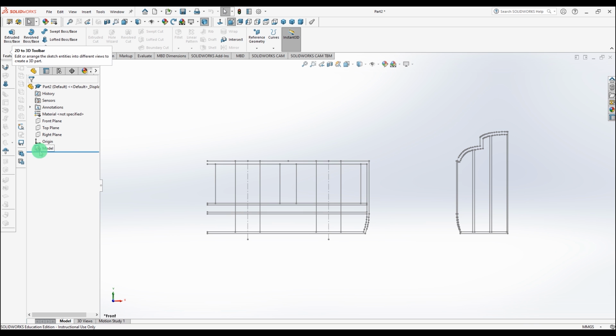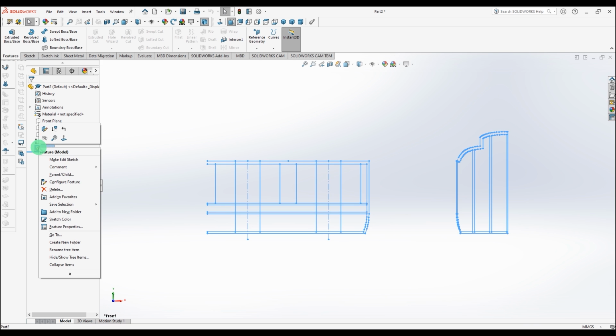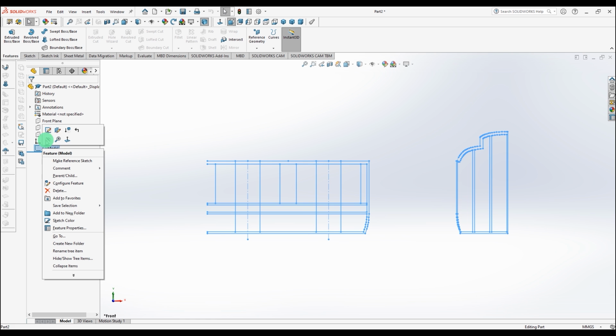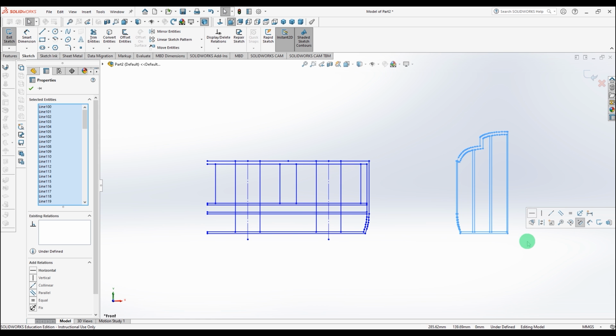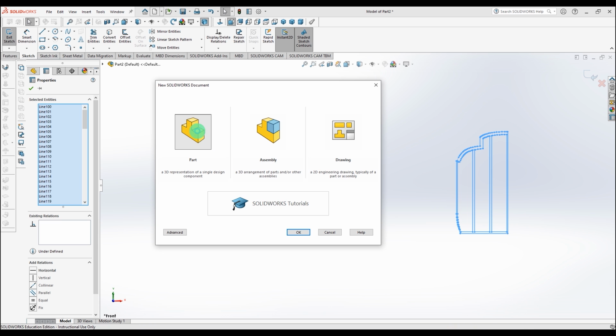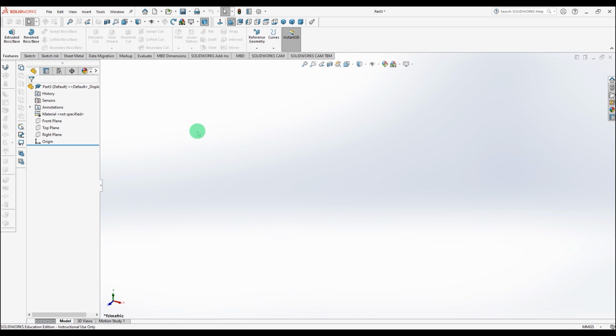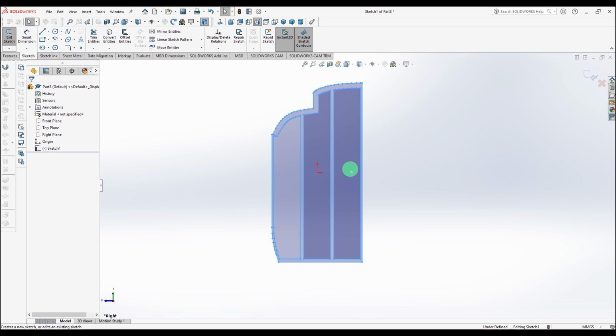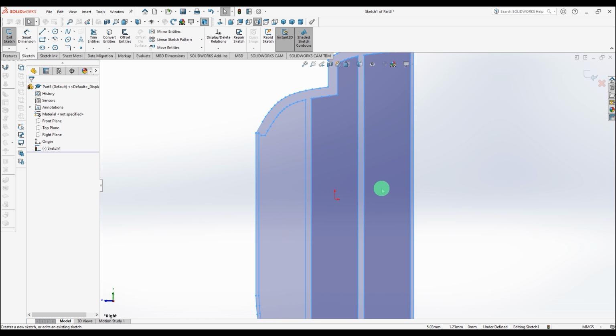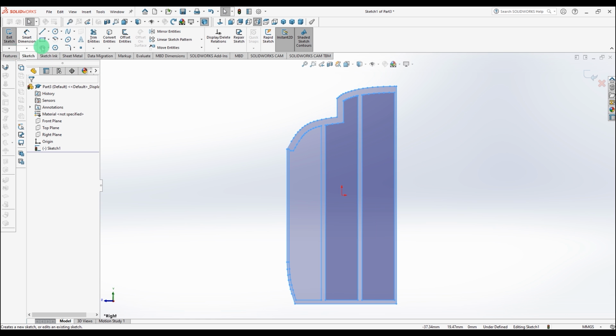Now, I could have created all of that in Solidworks. I could have done exactly the same process, but I'll just do it the way I like to do it. I don't think it takes me any longer, and certainly I then have the two-dimensional data, which is much easier to extract retrospectively. Let's say I've drawn this thing in 3D, but I've decided I want to laser cut some of the panels, I've then got to go in and export the two-dimensional sketches out of the 3D drawing, whereas I like to have all of that 2D data ready to go.